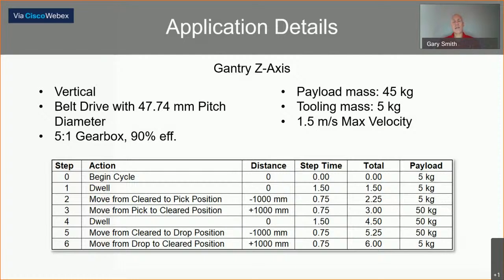We also have the same identical 6-second overall cycle time, but these are going to be synchronized. So when the x-axis is moving, the z-axis is stationary. When the z-axis is moving, the x-axis is stationary. So to accommodate for that, if you remember, we started off with the x-axis by immediately moving our 2 meters in 1.5 seconds. So here, we're going to be idle or dwell for our first 1.5 seconds.